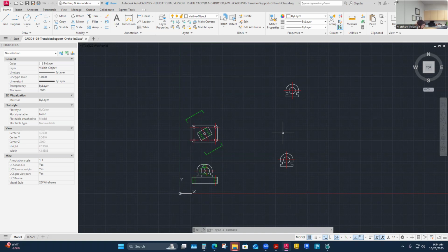And that trick question was rotated. There was some quiz, and I can't remember who pointed this out to me, where one of the answers was rotated. That's a gotcha question, because technically chapter 12 would call these revolved, and we're doing kind of a revolved and removed. But the word rotated does make sense. So I might write rotated underneath the view label, but it's actually revolved and removed. I would say I removed it and then I revolved it.